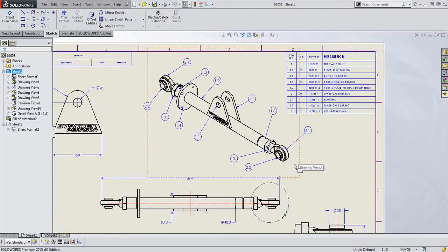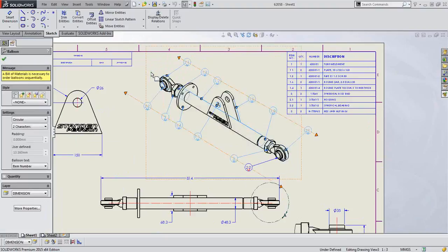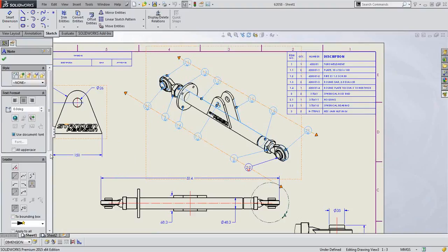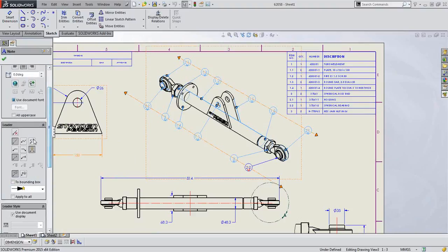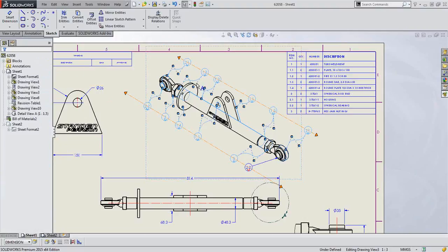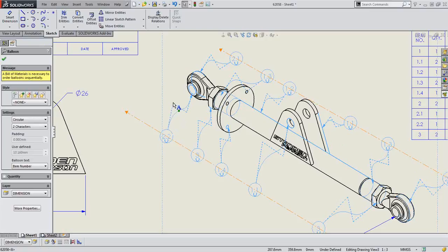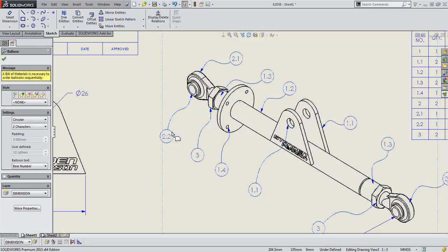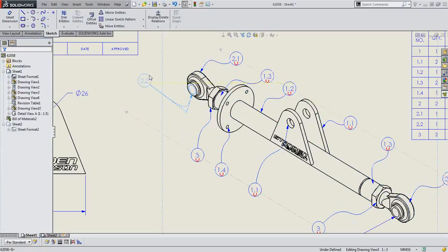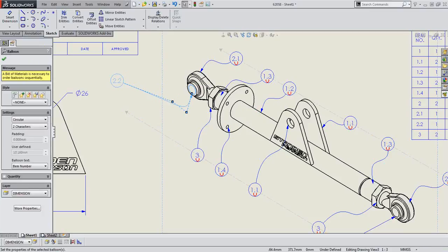You see this particular part, and you see this particular assembly over here. Now the assembly already has the balloons defined, right? So if I select this, and if I go for more properties, I have a new kind of leader which is called a spline leader. The advantage of this is that I can manipulate it to any size, any direction I want. You can apply it especially for the tricky parts which are very difficult to capture.